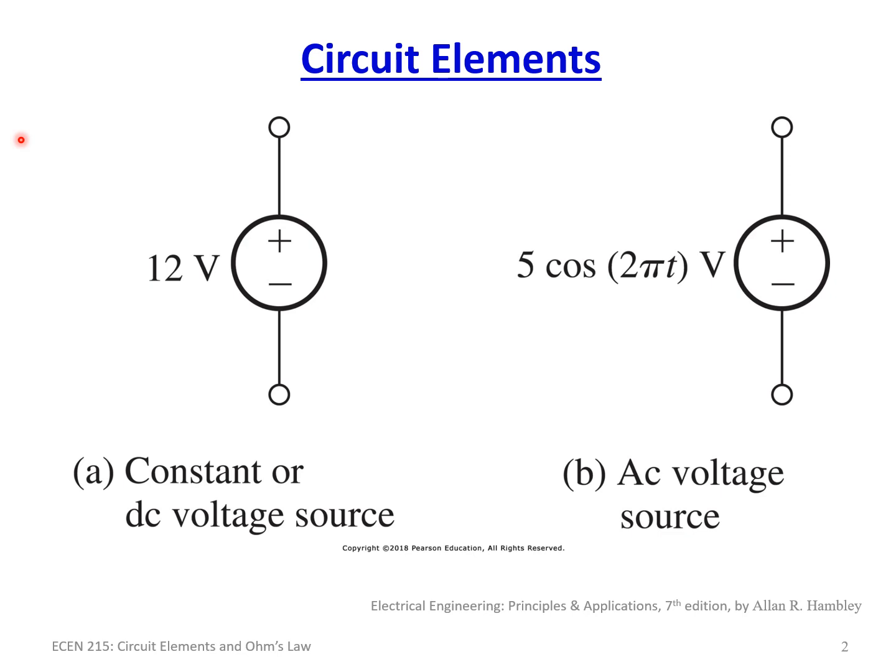When we get into Ohm's law in a few moments, if you put a short circuit across this power supply, in other words, you draw a wire between this terminal and this terminal, this thing would provide infinite current. The voltage across an ideal power supply is always the voltage specified. So this power supply would always provide 12 volts across the terminals, no matter what you connect to them.